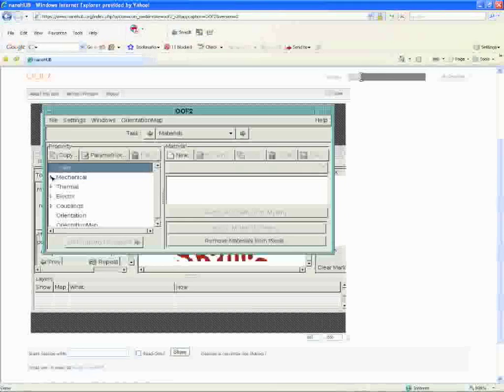Next, we have all the mechanical properties, like for example the elasticity. If we click on it, you can see that we can input isotropic or anisotropic properties. And if we click on anisotropic, you can see that you can choose the crystal structure of your material. Also, you can input the stress-free strain of your sample or the force density. Also, you can input thermal properties, for example, the conductivity of your material, or whether your material is producing any type of heat here in heat source. And we also can input electric properties like the dielectric permittivity. Also, we have couplings, like for example, the coefficient of thermal expansion or piezoelectricity or pyroelectricity.